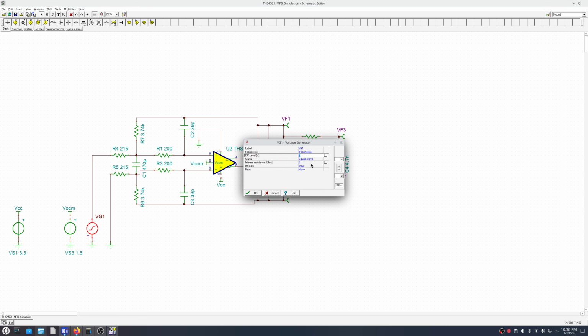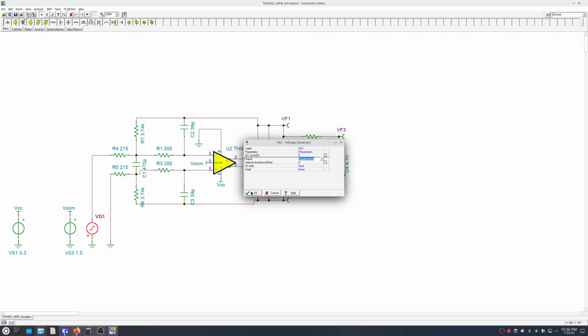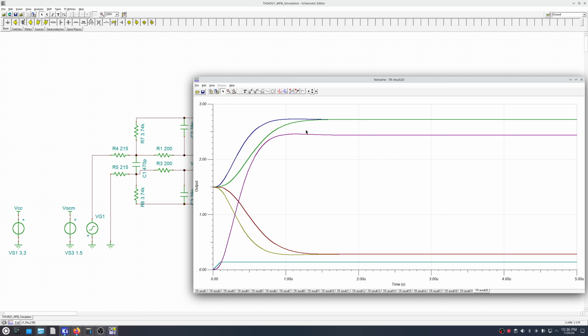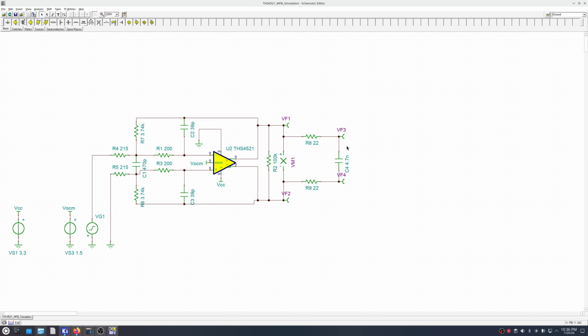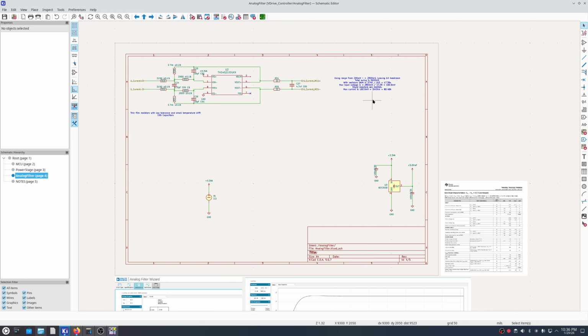So then with the 4.7 nanofarads we can't actually use that 160 or 150. I think this 140 millivolts was like best, so the signal is clean and we get the filter. So then we can calculate, so it's the 140 millivolts, and instead of max 80 amps we will have like 70 amps maximum. So we can write it here.